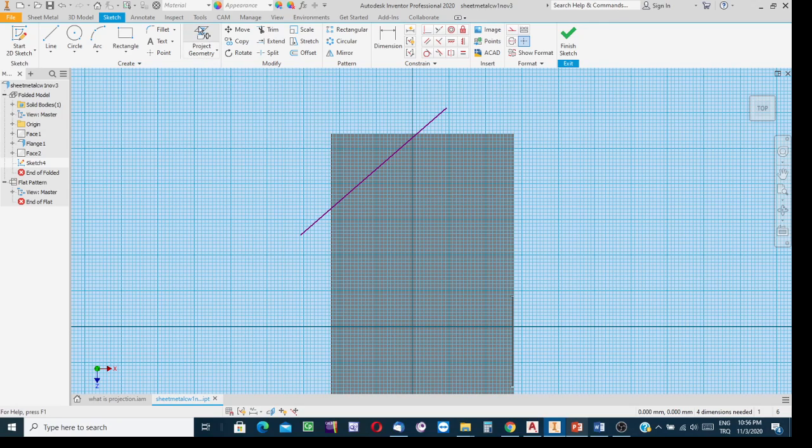You know the technique, the trimming technique. First, have the shoulders at this stage. While applying the project geometry process, have the projection of this edge, have the projection of the other, and then trim. Say that this portion is unnecessary, this portion unnecessary, and have the terminal points of the sketch precisely along the